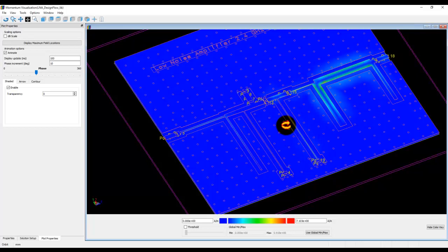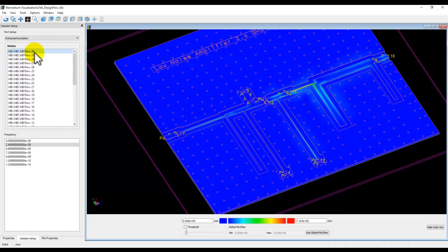All right, no prize for guessing because you have an amplifier device here, right? So whatever excitation, let's say minus 30 dBm, and if you go and look, currently we are looking at minus 30 dBm. So the power available here is minus 30 dBm, and here you have a 15 dB gain. So here you have minus 15 dBm. So obviously you have more current propagation going through.